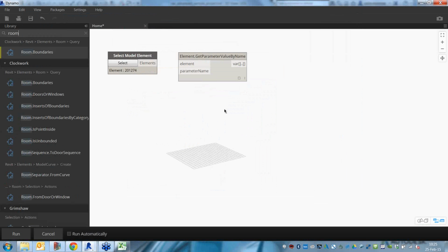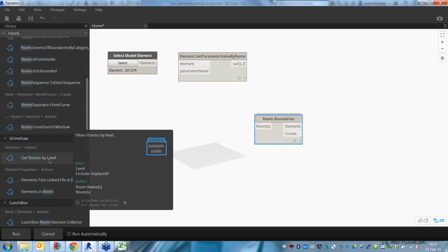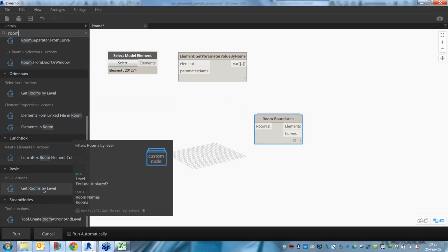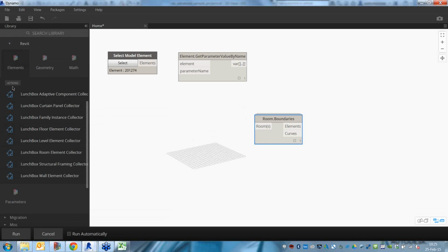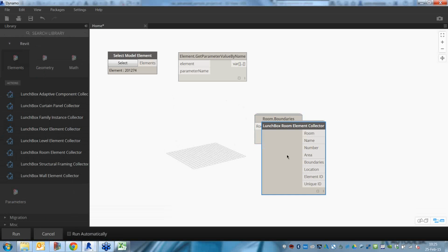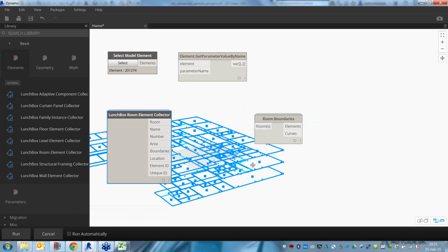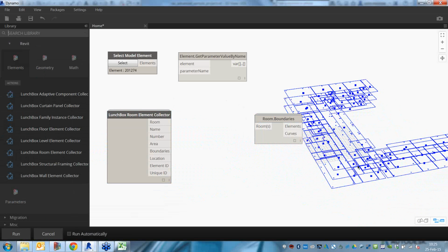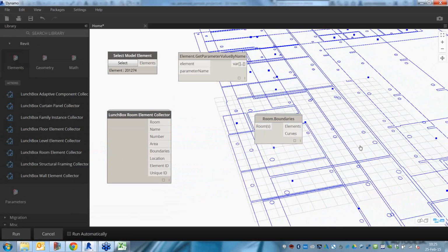Okay, yeah, so if I'm interpreting this correctly, there are certain rules, like BOMA area analysis rules, which have to do with, if you want to build a room that's 100 square feet, where you measure to depends on the condition of that wall. Exterior walls are typically measured from the face of interior, but interior partitions can be measured to the center of the wall, depending on the rule that you follow.